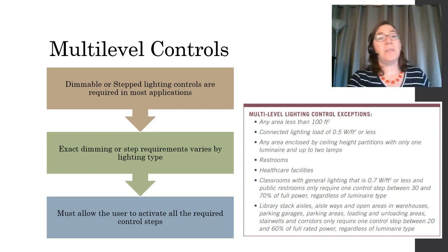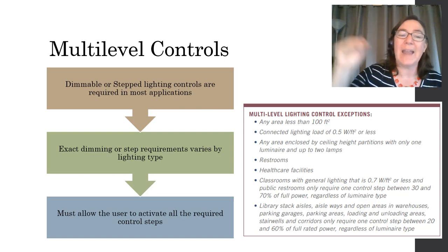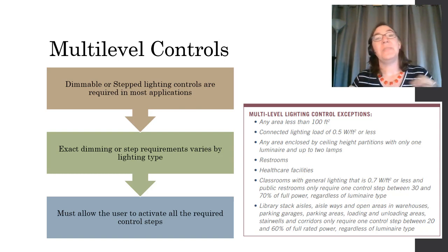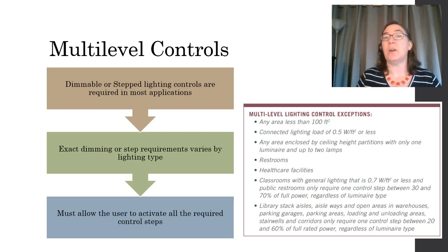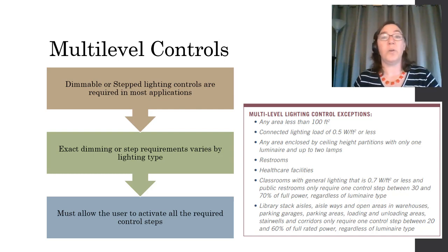All right. And the other requirement is that a user must be able to actually use these controls and activate the steps. All right, there are some exceptions. The exceptions are mostly for very small areas, very low amounts of lighting. Also, restrooms don't have to be dimmable, healthcare, and some specific other exceptions.